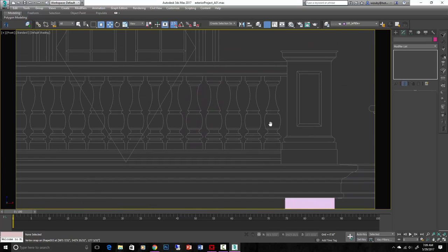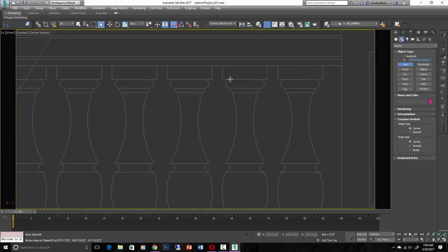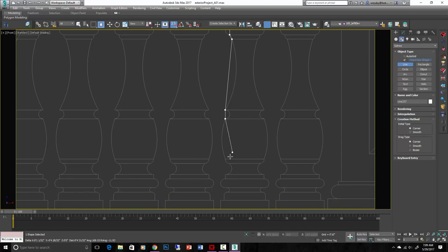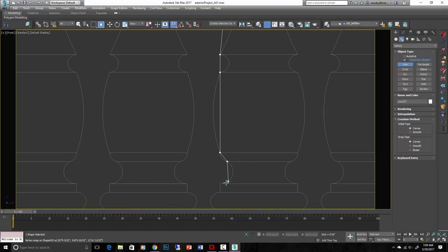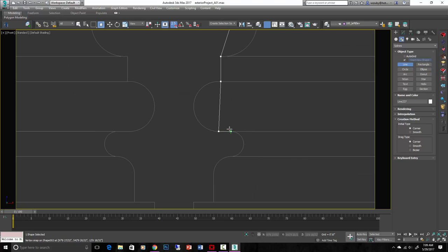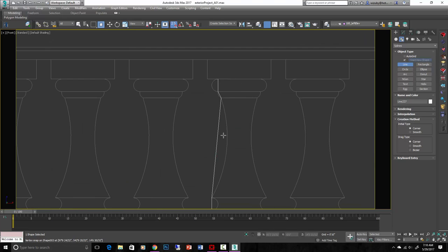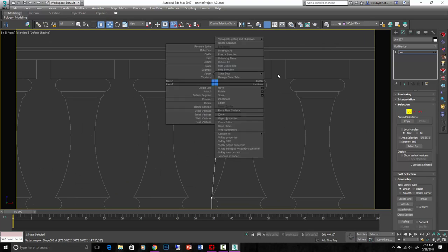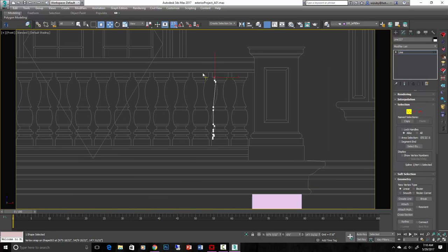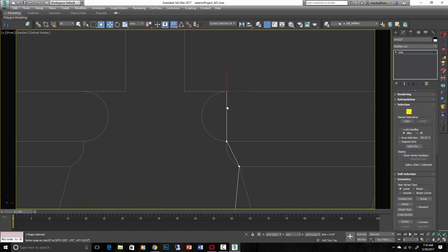One last thing, let's do the lathe modifier. Again, we'll go to our trusty splines. We'll start tracing the basics of this shape here, hitting all the important points. To there, and then this is a square block on the bottom, so that's not going to be lathe. The lathe is going to rotate this profile around in a circle. Okay, let's just select all these and make them into Bezier corners. And then at each one we can adjust.